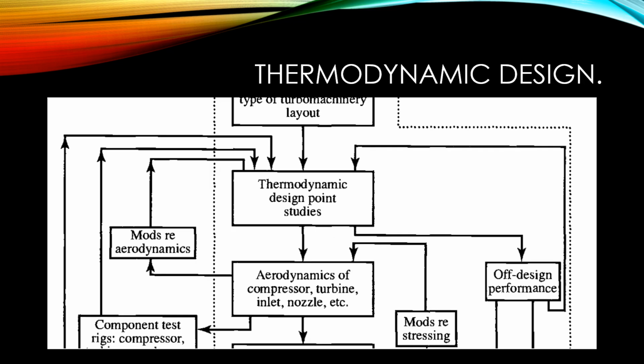Thermodynamic design. These are detailed calculations taking into account all important factors such as expected component efficiencies, air bleeds, variable fluid properties, and pressure losses, and will be carried out over a range of pressure ratio and turbine inlet temperature.